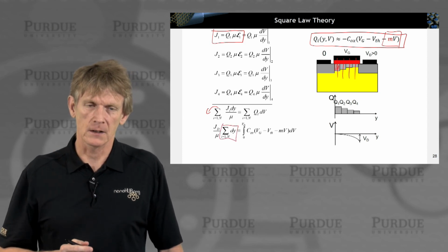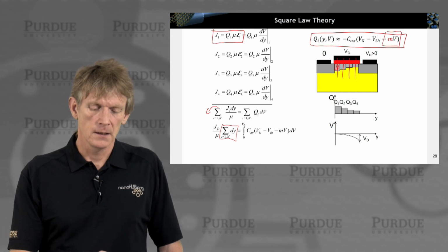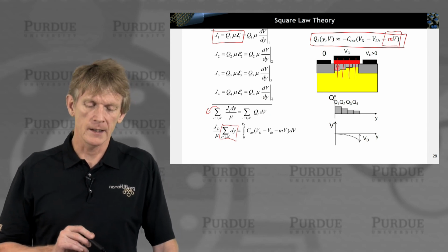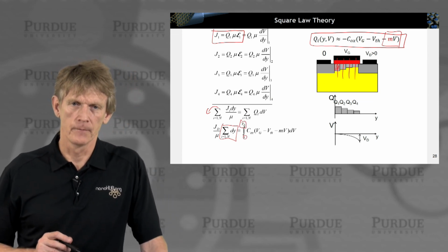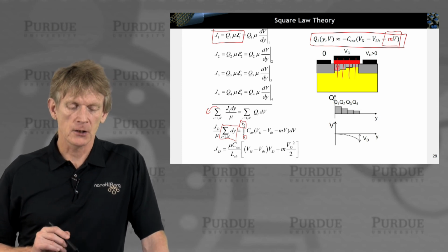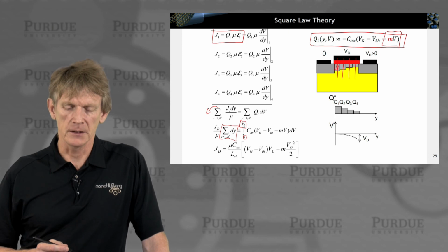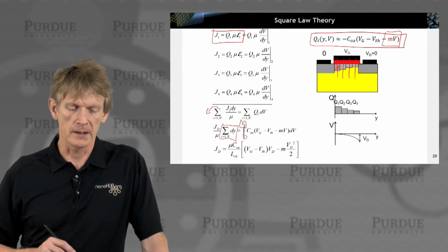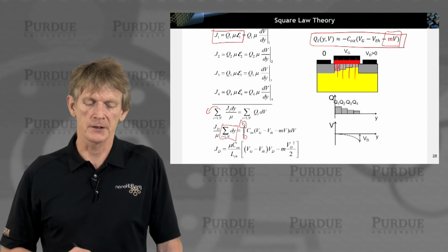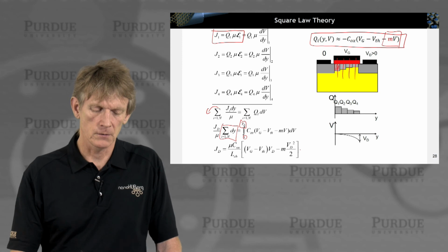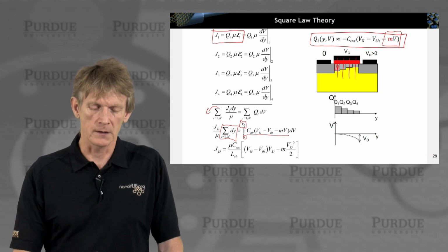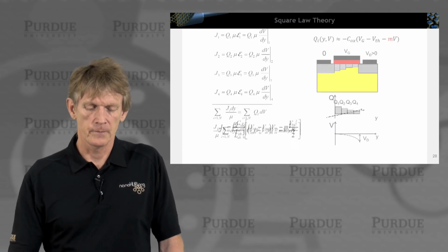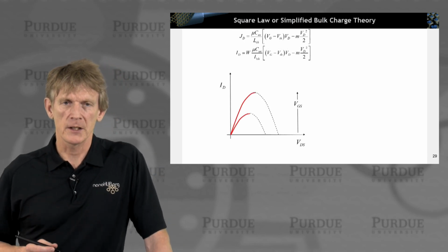So nothing sophisticated here. And if we do this right, we multiply here by the dy to effectively integrate over the drain voltage this expression. Okay? Now, we can integrate up this linear graph very easily as a function of applied drain voltage, and we basically come up with a square expression as a function of drain voltage. Okay, so integrate this expression here with dV up to drain voltage, you end up with a linear term and a square term. Okay, so here we are. We have an expression for the current.